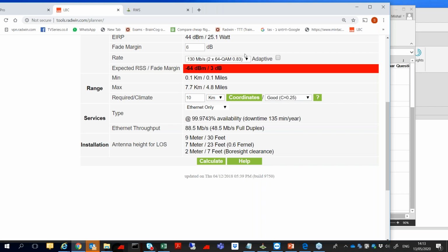But if the air interface is interfered and there are noises, we can expect deterioration, and sometimes it's better to go to a lower channel bandwidth and to guarantee a higher modulation. It's always a trade-off of channel bandwidth and modulation, which ensures a better throughput.